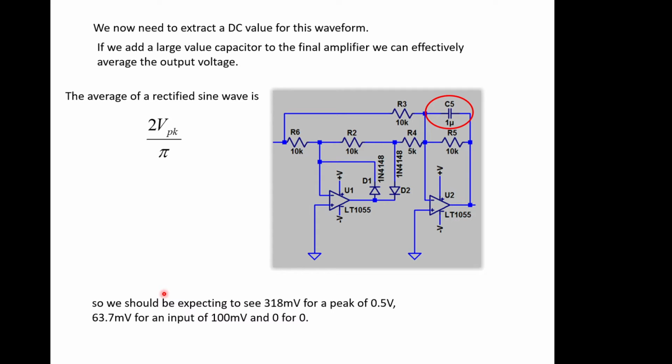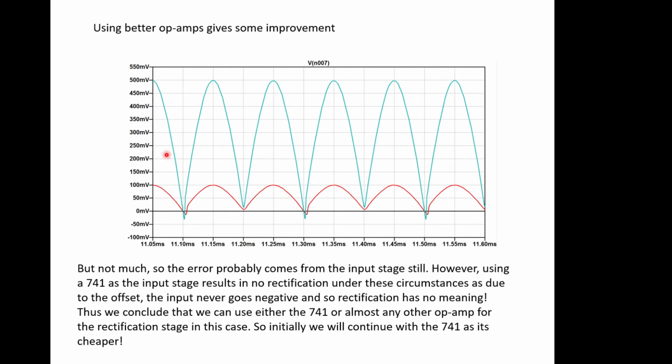So once we've got that, we've got effectively a DC waveform, because the waveform that we're getting has a DC average, okay, but it's not smooth. We've got a bouncing signal. And we'd like to have a nice DC flat level, so we need to work out what's the average of this waveform and get that out as a signal.